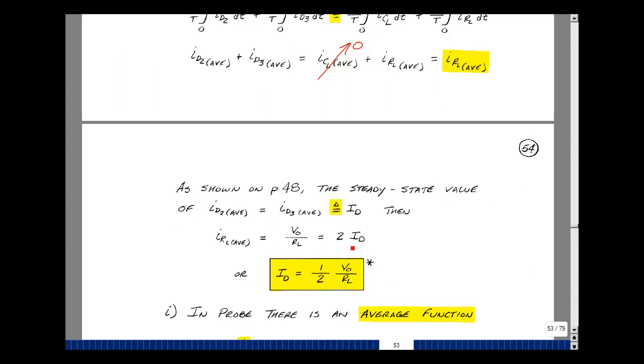This particular number is also a datasheet rating. This is the repetitive surge current on the average. So we need to make sure we pick a diode that can withstand this particular number. These are some of the properties of a filtered full-wave rectifier circuit.